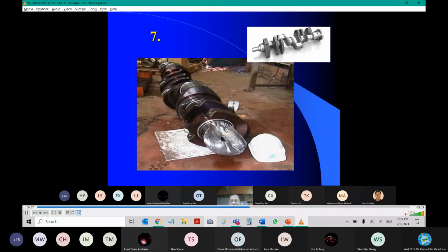This is a crankshaft. Crankshaft, this is when it is good. That's what the shape looks like. And the crankshaft is actually transmitting power from the reciprocating piston through the connecting rod, and then that power is transmitted on the left-hand side there to the wheel or the flywheel of the engine, and then the flywheel will actually be connected to the clutch.